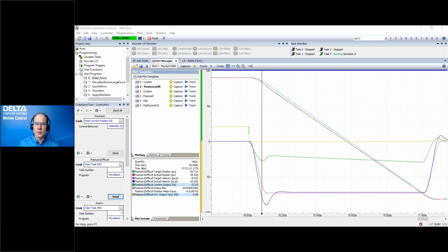If it's off significantly, then yeah, you need to set the output bias to take care of that null. The integral term can take care of a little bit, but if there's a lot of it, then you start getting the problems that we have with the integral term, that it can overshoot. An integral term typically doesn't always respond all that fast. It integrates over time, that's a little bit slow. So yes, if you have an offset on your valve, you should try to fix it with the output bias first, and then the integral gain doesn't have to work so hard. Good question.